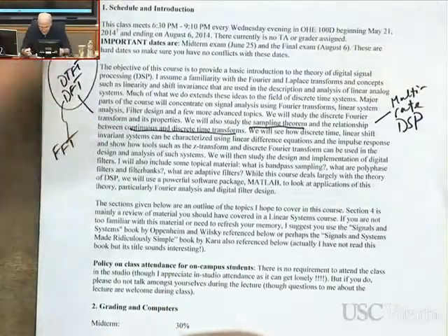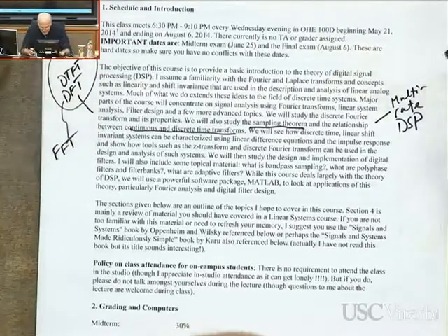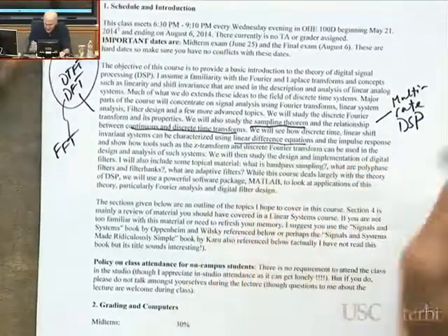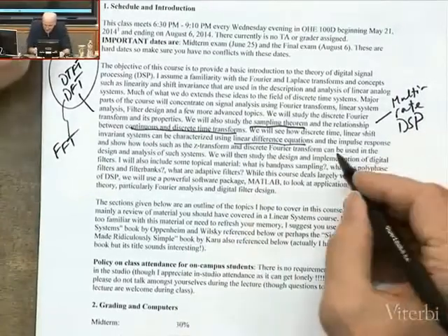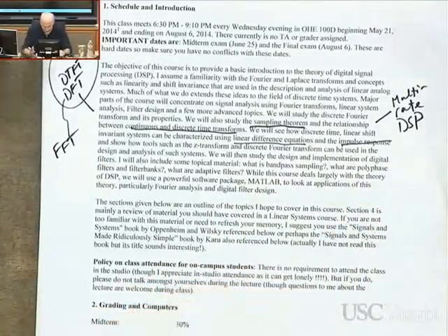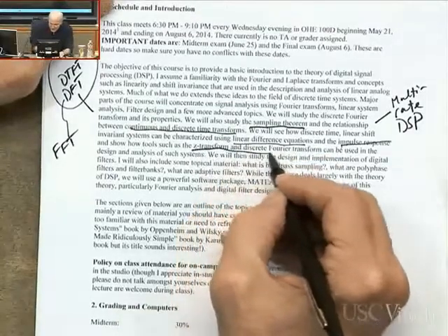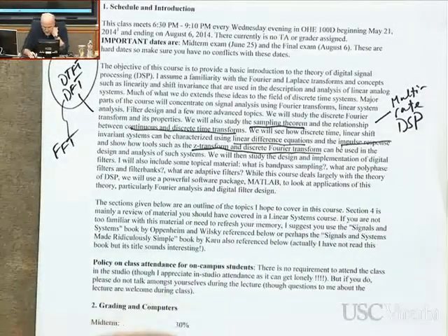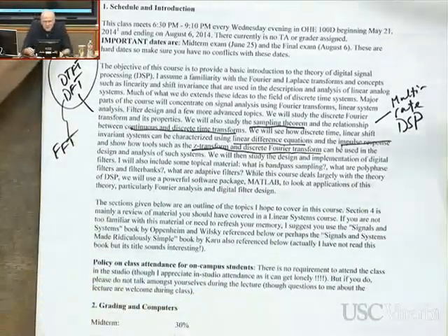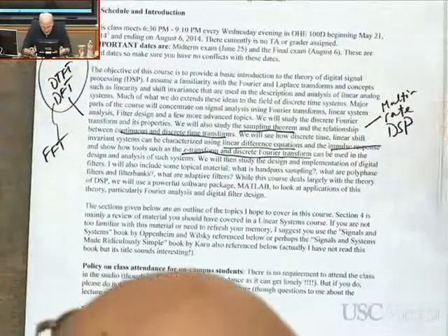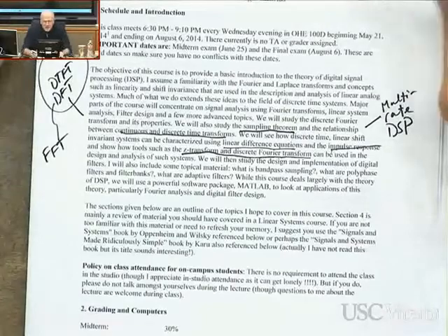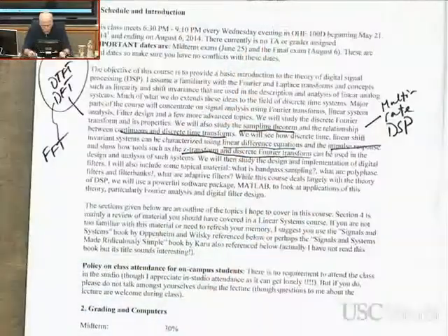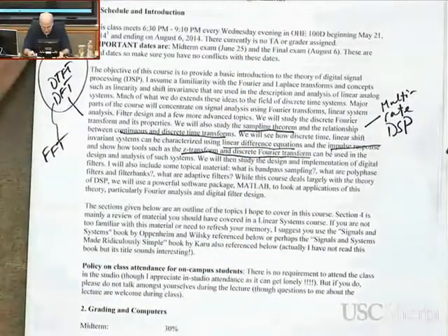And then we will talk about linear shift-invariant systems, how they're characterized in terms of block diagrams and linear difference equations, the impulse response filters, and also something called the Z-transform. Many times I ask people who have had exposure to DSP and linear systems, and most of them have heard about or know some discrete Fourier transforms, or at least discrete time Fourier transforms, but not as much about the Z-transform. And the Z-transform plays an important role in digital signal processing, as we will see.